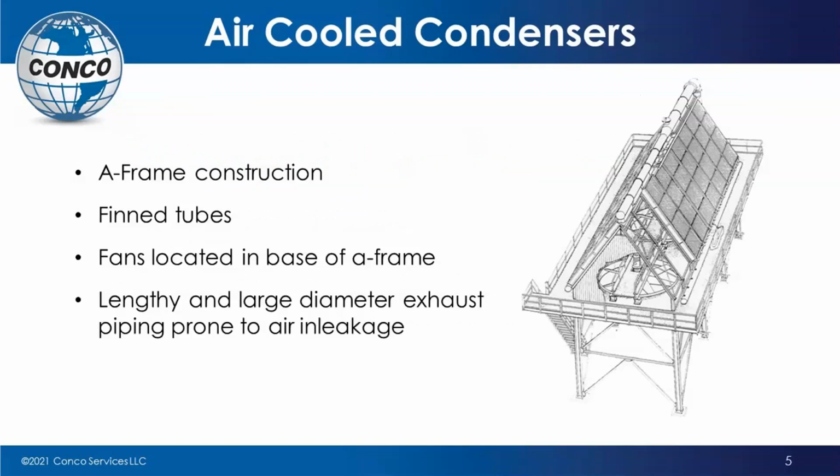Taking a look at the condenser itself, the air-cooled condenser, I'm sure many of you know this, but I just thought we'd go over it because this plays a role in the cleaning and in the leak detection of this particular unit. A-frame constructions typically with the fin tubes and the fans usually located in the base. For some of you, we have seen some inverted where the fans are at the top.